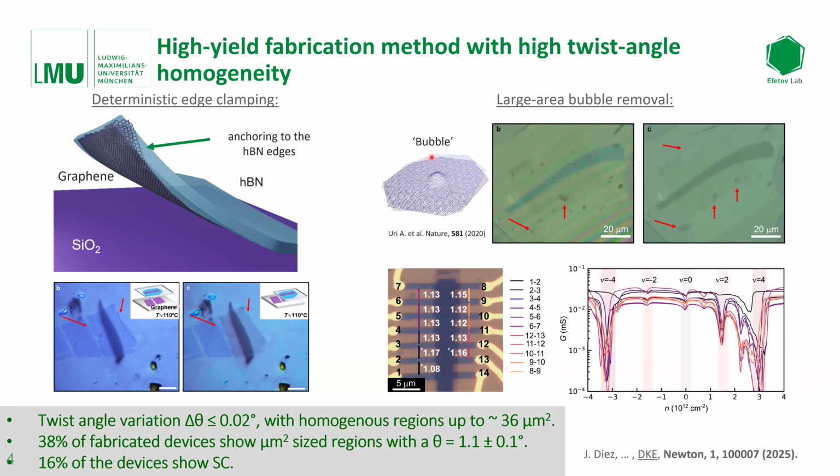And of course, these bubbles are heavy strain centers, and around these bubbles, strain is quite pronounced. So, for example, we improved this bubble-free assembly by playing with the temperature in the assembly process, which really helped to remove many of the bubbles in the active device region. And with this, we thought we stabilized the process quite a bit.